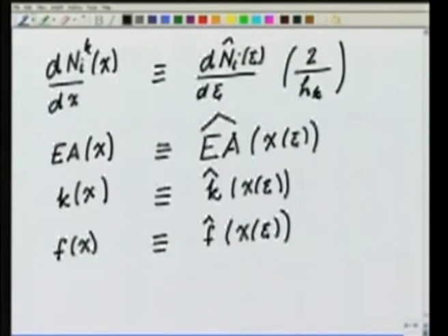So, this we can do and take all our material constants, the loading data, from the physical element to the master element. So, now let us use these transformations to redefine the integrals over the master element. Remember that we have done all this to bring the integrations from the physical element to the master element.